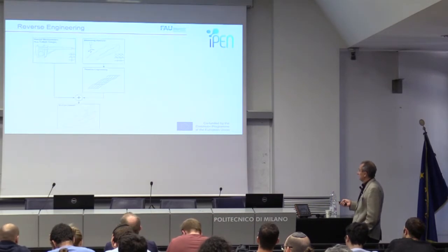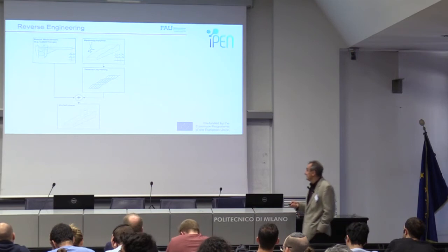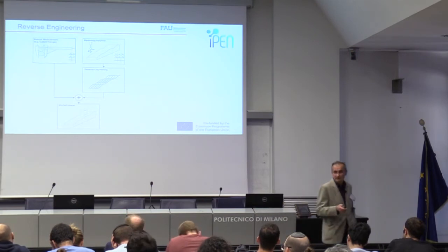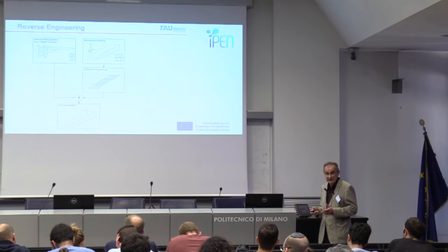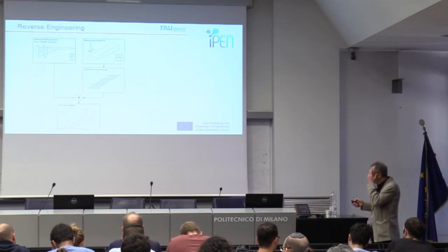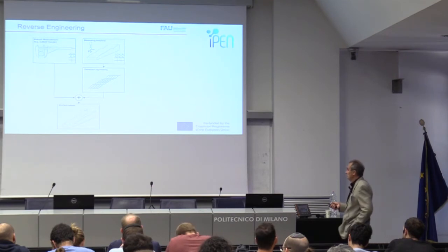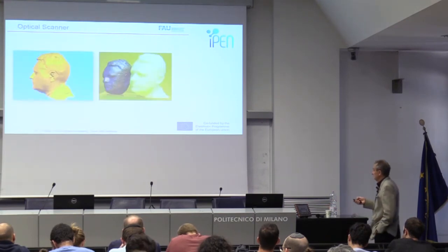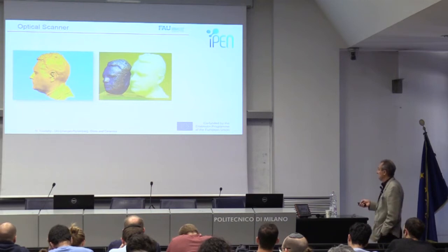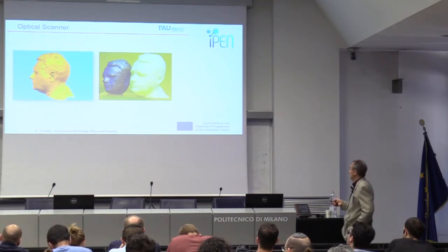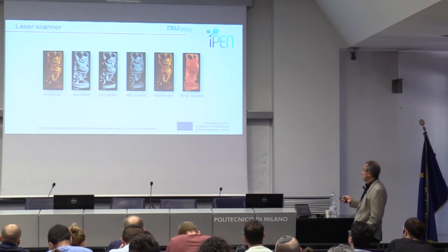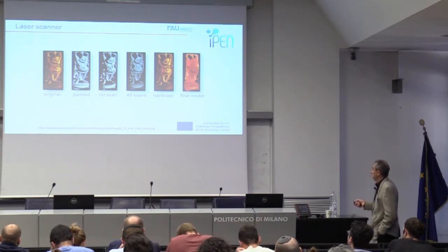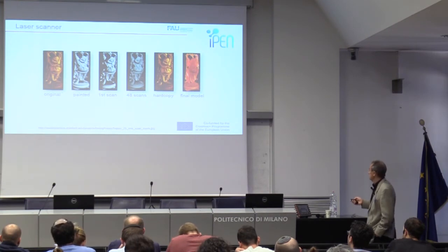But the problem is often the reverse engineering, because if you have something and think, okay, it's very nice, you should of course measure it. You can measure with laser, you can measure with computer tomography, and so on. And after that, you should make the 3D computer modeling. And after that, of course, you can print. How to print? Just now, we will see. This is also made in our chair after laser 3D measuring, and it's also to make some figures from the scans. You can use nearly 50 scans, and after that, of course, you can print the final model.